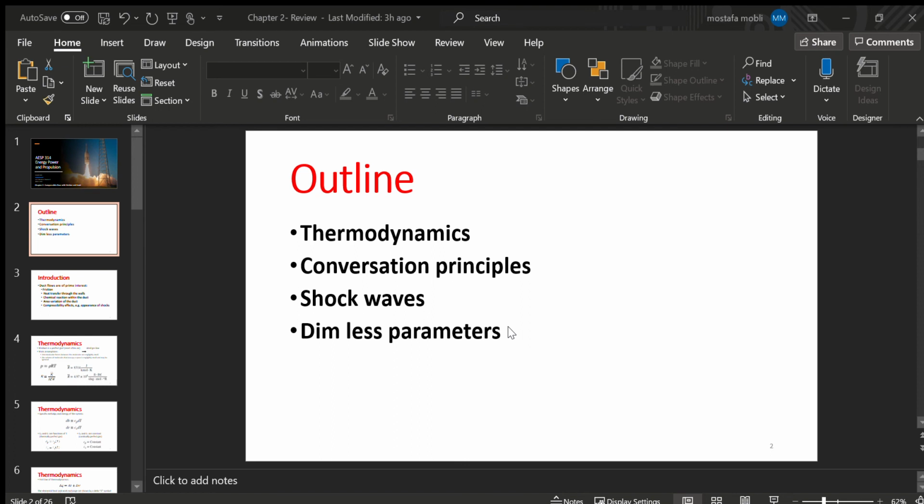And we have the equation for partial P over partial rho, and just use gamma P over gamma rho. U squared can be equal to that. And based on the ideal gas law, P over rho is equal to RT. So U squared is going to be gamma RT, right? And this is the speed of that sound wave if we use A, right?